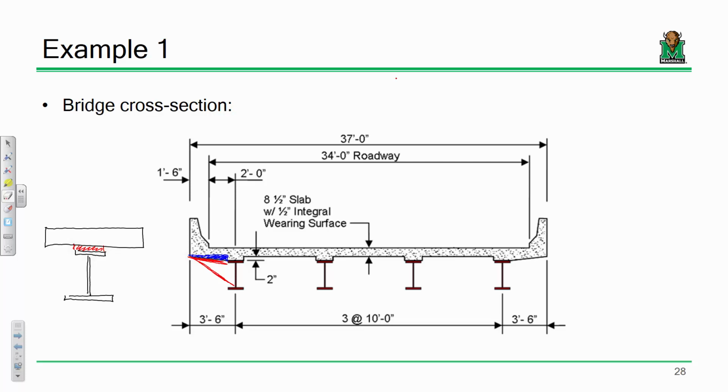Will that be more than the normal daily loads, or is it less? Let me try and answer that carefully. It's probably not more than the loads, but it could result in higher stresses. Ultimately, when you're looking at design, moments matter, but M over I to get stresses is going to matter a little more. When you're pouring the wet concrete and placing the deck onto the girders, it's a non-composite girder. So your moment of inertia is a lot lower.